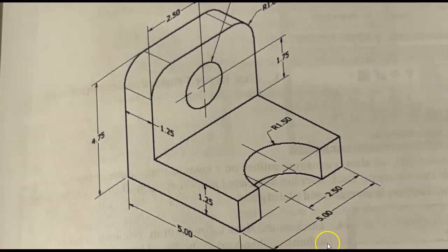In order to do that, we do have to turn on the ISO draft. So we can click on the ISO draft here. Just another place, we can go over to our customization tab, which is right down here in the lower right-hand corner. We can also turn it on that way, to make sure your isometric drafting is showing here as well. Once your isometric drafting is showing, then you can click on the ISO draft tab to turn that on. At this stage, I am in the ISO plane left, which is where I want to be. So we'll keep that there.